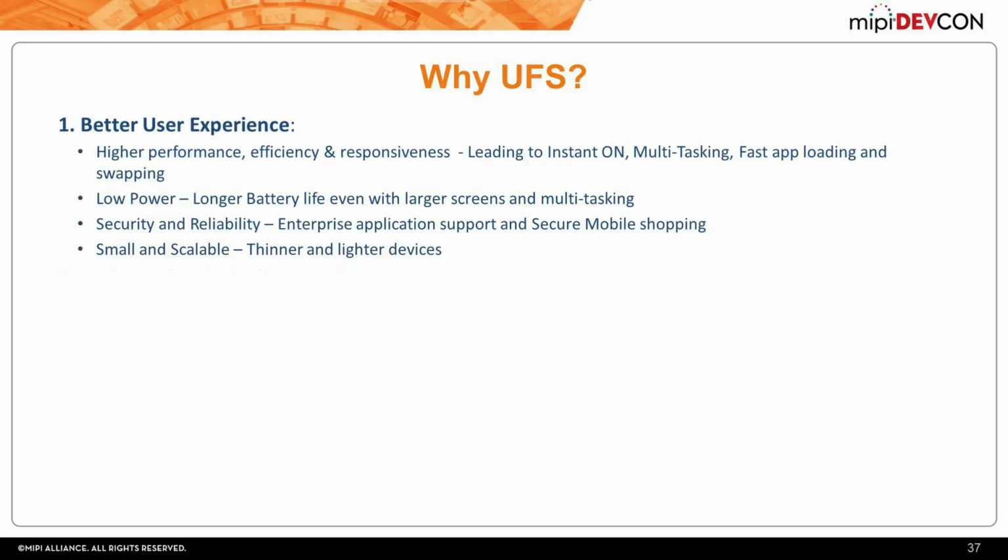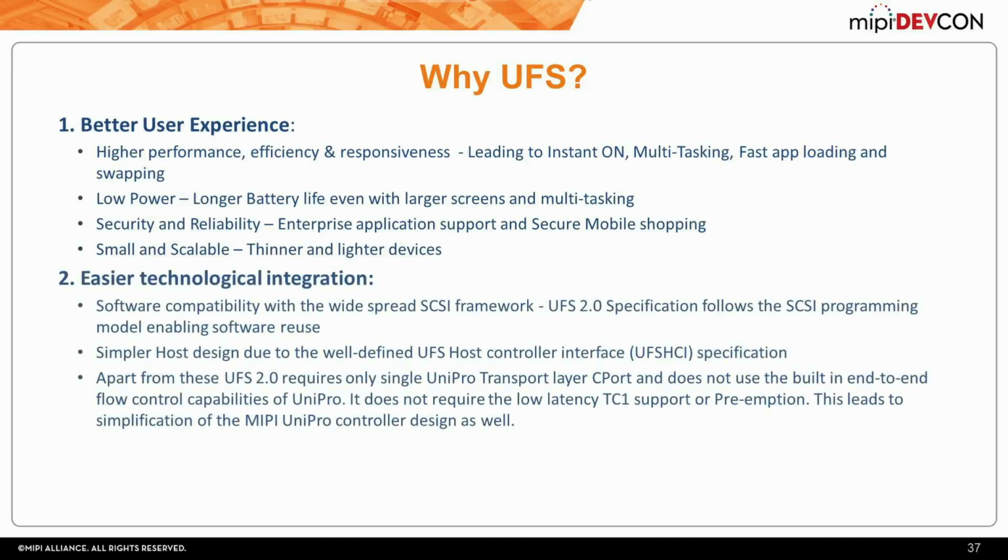Again, lower power. It takes advantage of using M-PHY for the physical layer, which is inherently very low power. It's scalable and small also, and it's easy to build in with the technical infrastructure because it uses the standard SCSI model and SCSI framework. So software at the higher levels just sees them like SCSI devices. It makes it very easy to integrate that into a system.